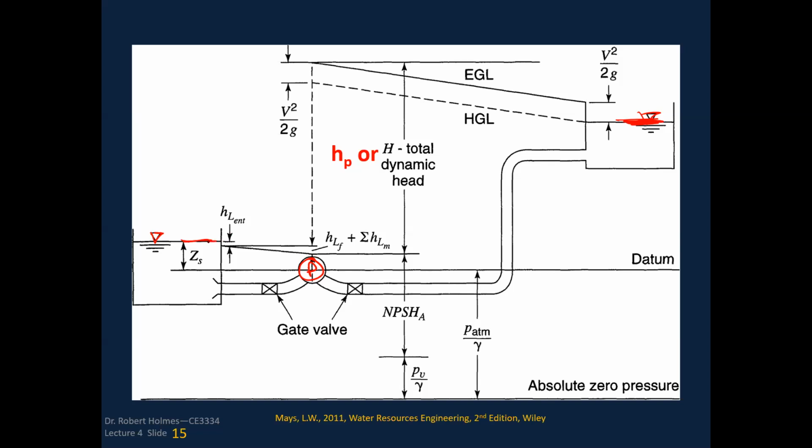You can see that for the total head here, you've got some losses due to entrance into this pipe. So you've got some head losses there. Then we've got further head losses due to friction up to the pump. Once we get to the pump, we add in a whole bunch of head due to the pump head that's entered in. So this is the H sub P. Then as we move over to this reservoir, we have losses going through here, maybe the minor losses due to the gate valves. The bigger loss is going to be the friction loss, that's the water going through this pipe.